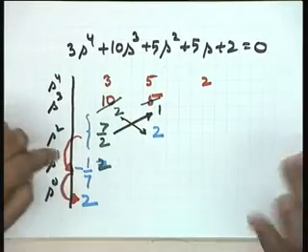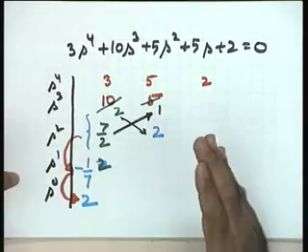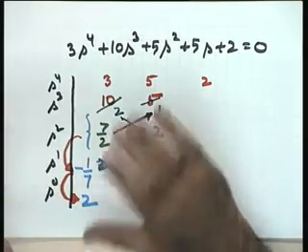Yes, we have not yet come to that particular situation. If this is the situation, yes, the roots on the j omega axis do not exist. I am going to come to that situation also. So, it means the Routh stability criterion has got an extension. Yes, if all of them are positive, then definitely all the roots are in the left half plane. If there are sign changes, the roots are in the left half and the right half plane, and the number of roots in the right half plane is equal to the number of sign changes.